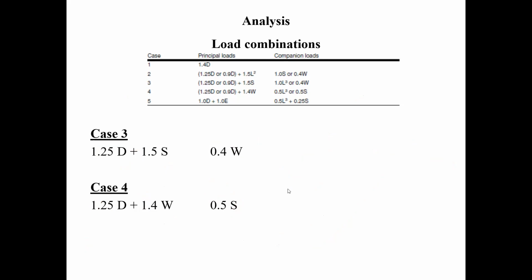Sir? Yes. Do we check for shear or deflection in this? Yeah, you check for shear. In other words, for shear, you take the WF from this value here. Yeah, that's what you do for shear. And for deflection, what do you do? Well, isn't it L over 360? Yeah, I understand, but what do you take for a W? The W, if you want, the case 3. No. Yeah, well, you take.